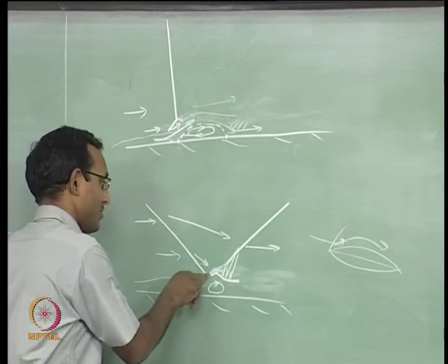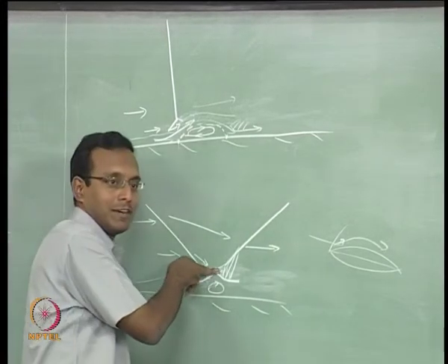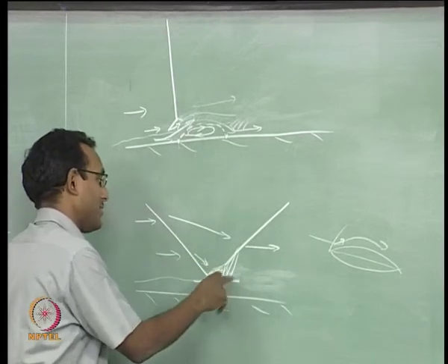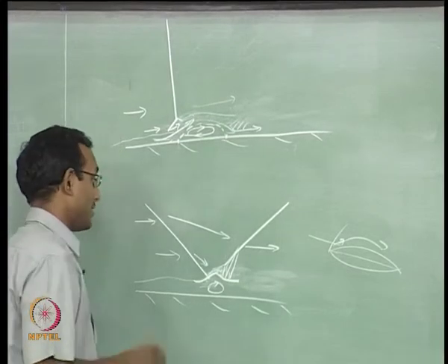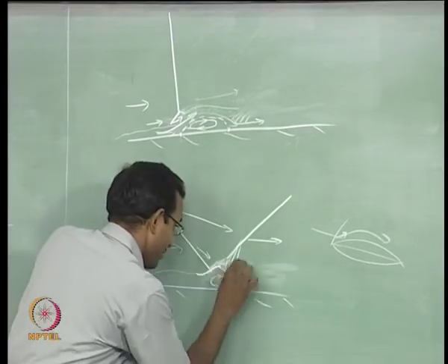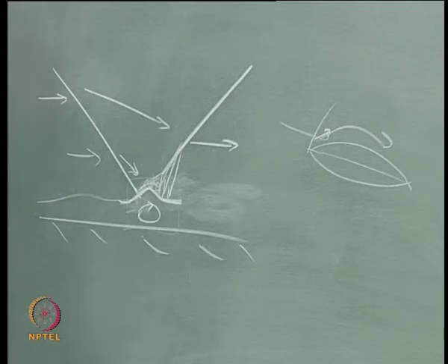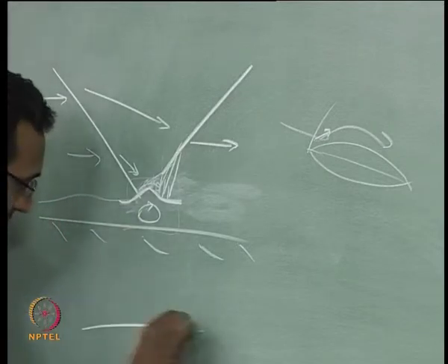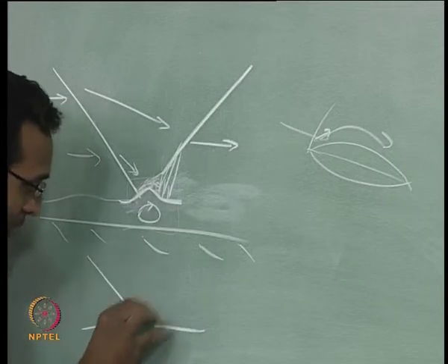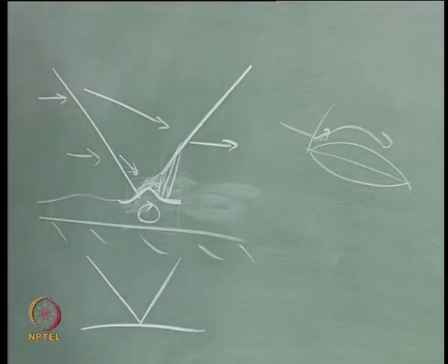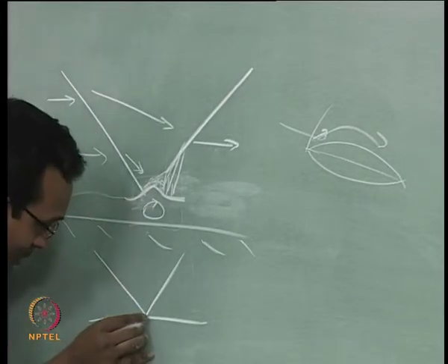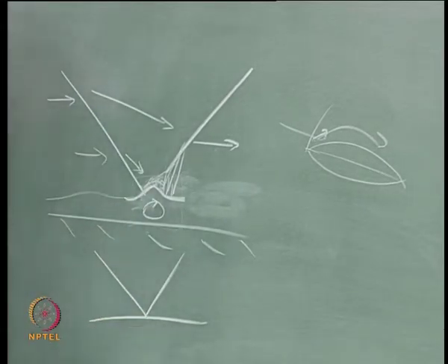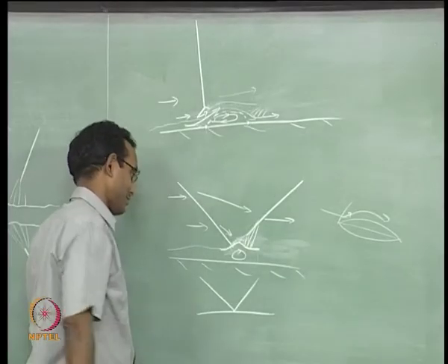Okay, some of these compression waves will be negated by the expansion waves immediately after, but after that the remaining things will just interact to form a nice clean shock. If I zoom into any boundary layer very close to the wall, this kind of thing will happen. If I zoom out and go far away and see what happens, then I will just see a wall, shock just bounces off the wall. Depending on the scale of the problem, this whole thing may be happening inside this small zone here. Depending on the scale of the problem, I have to think about it.